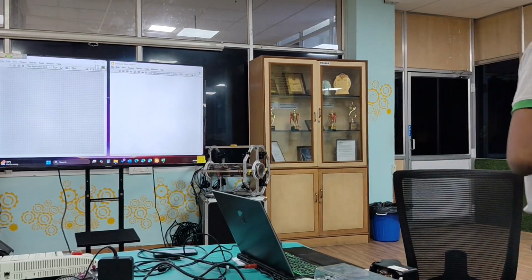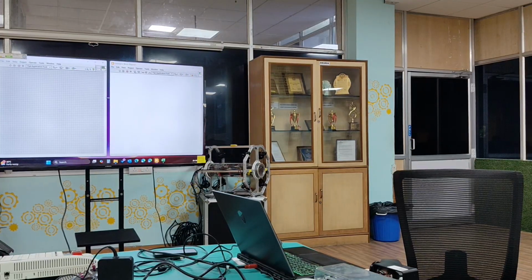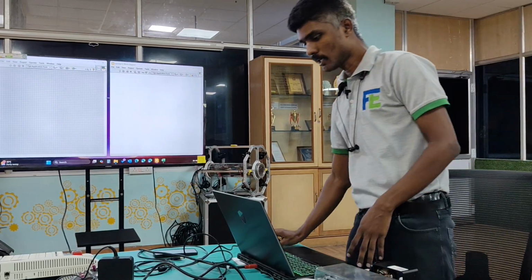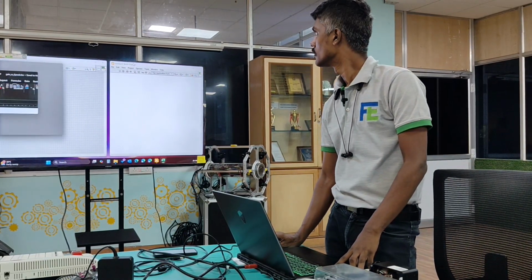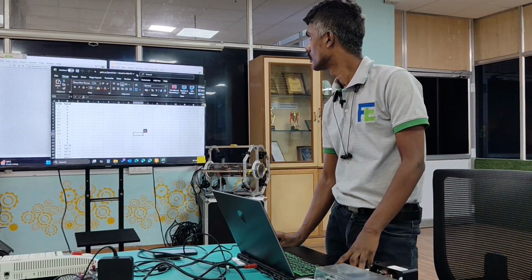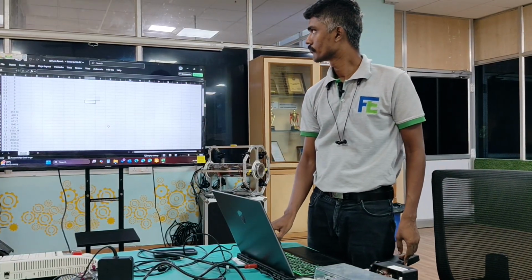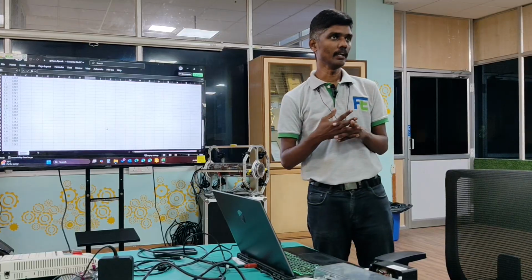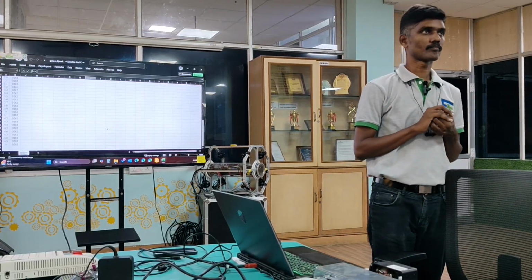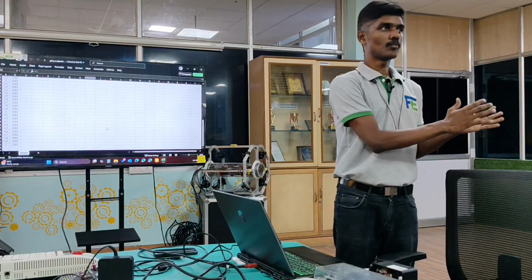For example, if you are given any unknown system, give it known values. For this system, I don't know the transfer function. I got access to the system only this morning. So what shall I do? I will slowly change my input value. If I give the amplifier input as 0, what is my output? 0.1, what is the output? 0.2, what is the output? Similarly, I gave some known values, 0 to 10, 0 to 5, and I recorded the speed values. From this, I am going to build my motor system model.